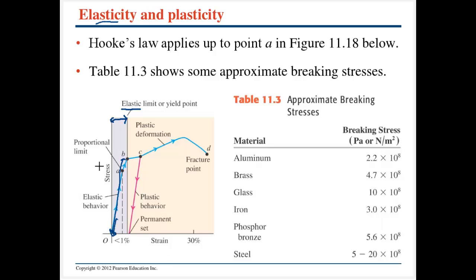If you apply too much force and you stretch it too far, it's going to go into this plastic region where essentially it will never return to its original shape. So if you apply too much stress and stretch it too far, then the shape will never be the same again. And if you keep on applying more and more stress, more force, at some point the material will fracture. That would be called the breaking point, or the breaking stress.